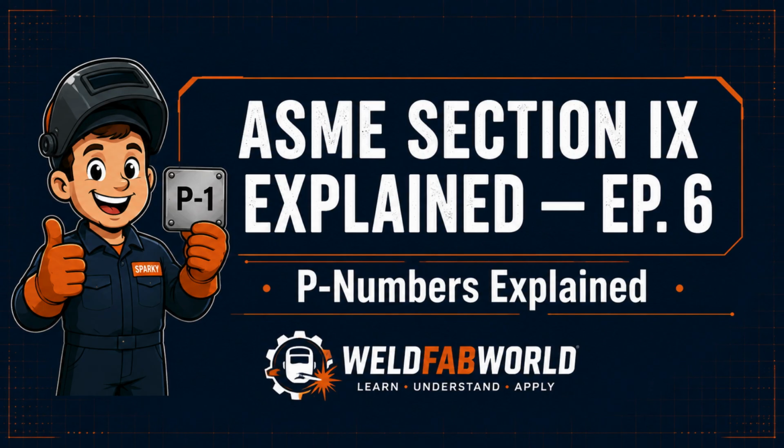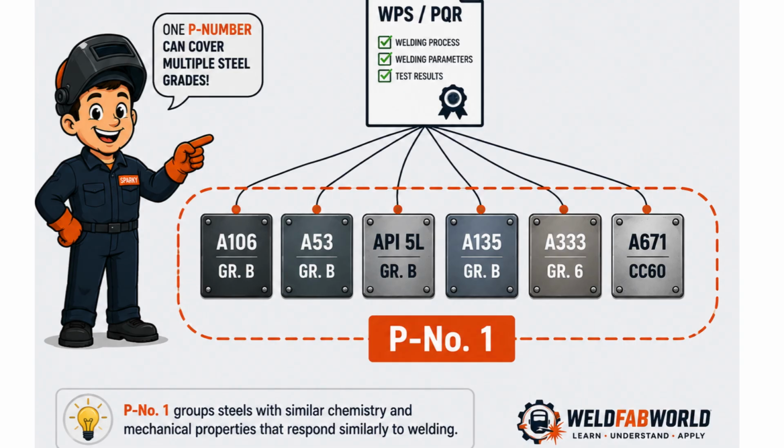We just spent a whole episode on essential and non-essential variables, and P number is essential in literally every single process table. Today we're finding out exactly what it means, and why it matters this much. P numbers exist for one specific reason: to reduce the number of procedure qualifications you actually need. Base metals with comparable chemistry, weldability, and mechanical properties get grouped under one P number. So instead of qualifying a separate WPS for every individual grade, one PQR can cover an entire family of materials at once. Weld one representative grade from the group, and you've effectively qualified for all of them.